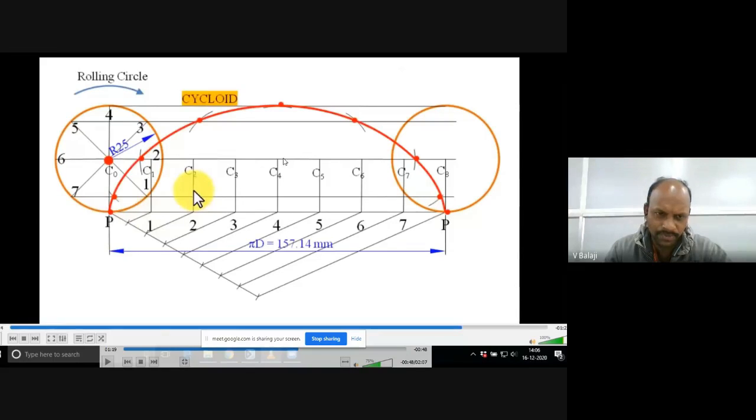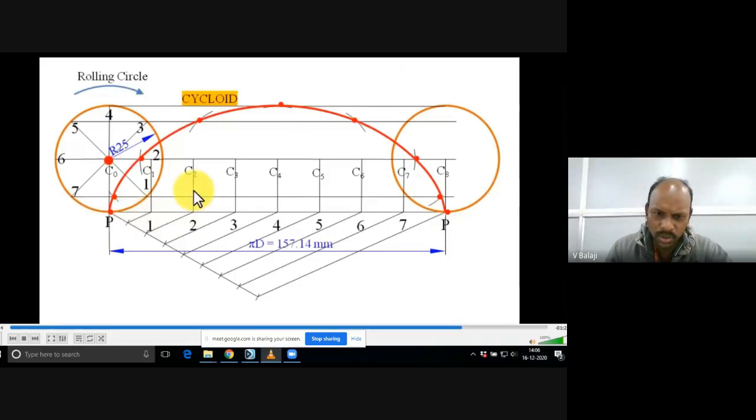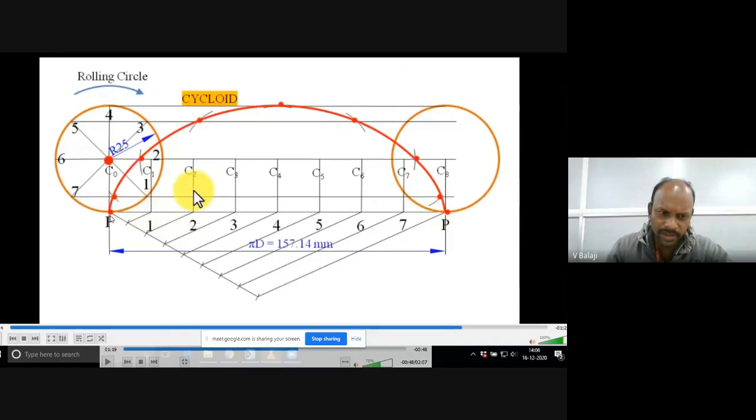Apart from that, so line division method here, drawing parallel lines, drawing perpendicular lines, horizontal lines 1, 7. Okay, passing through so many lines we have got, right. Those are not necessary to show with HB pencil. You can use 2H pencil. Okay. This particular curve must be highlighted. Okay.